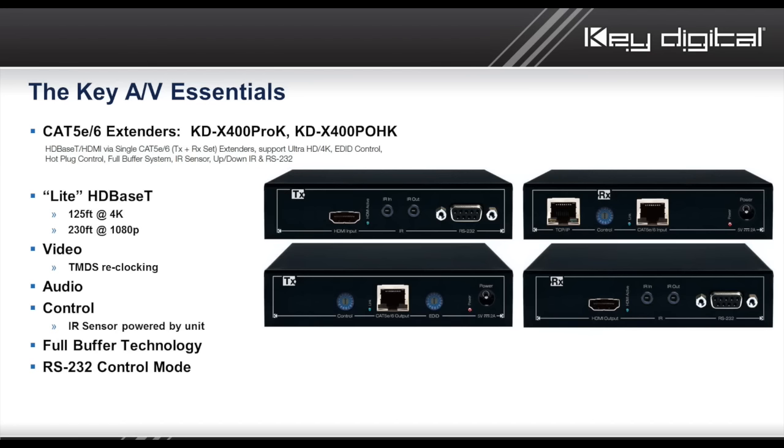What's different about this, though, than the 200? Two main differences. Number one, your RS-232 and your IR are on completely separate ports, so you don't have to choose IR or RS-232. So if you'd like to extend control to a device plus talk to the transmit unit to collect status, is my monitor up, or to collect status of the system or command our unit.